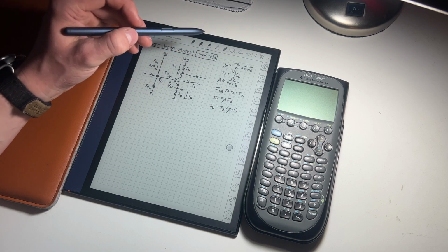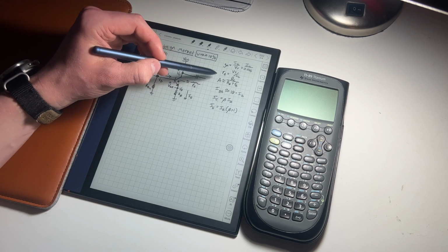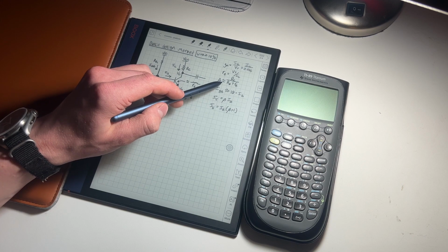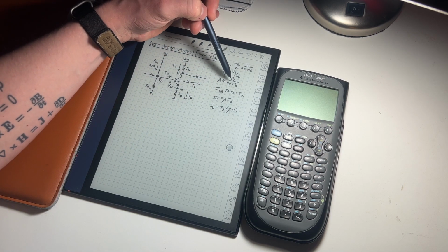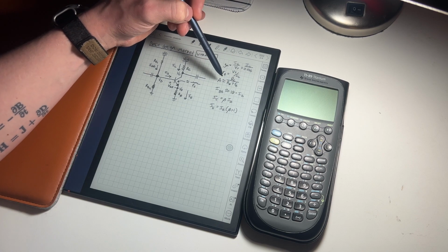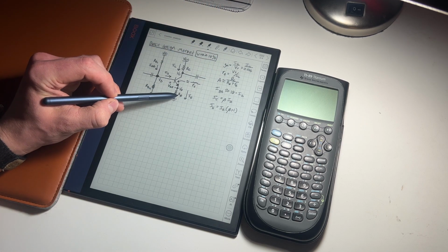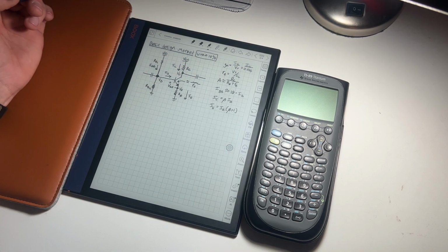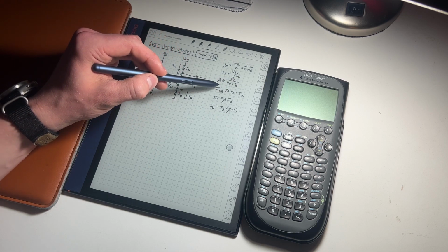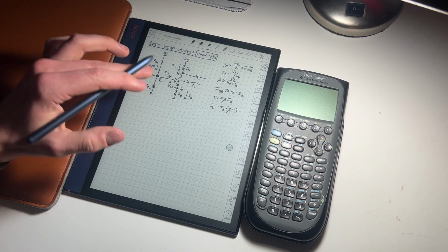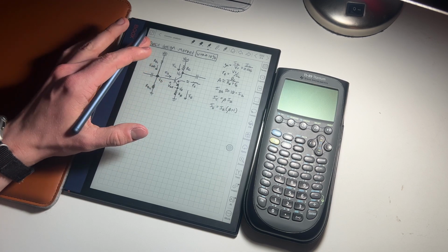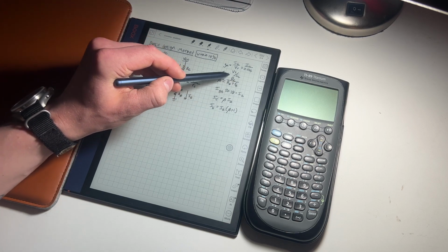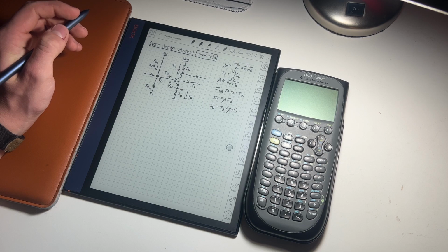Once you know this, then you can move on to this third equation, A, where A is the voltage gain of this amplifier. And you can see that the voltage gain is determined by RC over the sum of big RE plus little re, which we found in the previous equation. That is what completely determines your gain. Now the bias point and everything will also determine your gain, but when you do the biasing correctly on this voltage divider here, your gain is going to be very close to what you come up with.